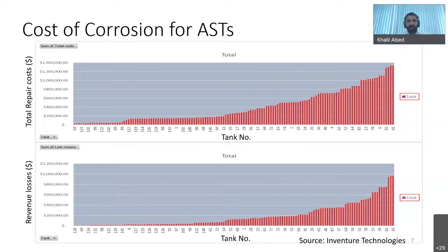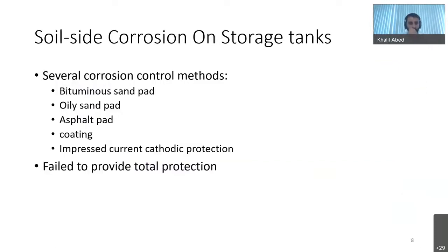And this is where protecting the tank bottom, for example using VpCI technology, can add value to the clients by maximizing the tank performance, minimizing the probability of failure due to soil side corrosion, and rendering the OpEx related to the tank floor inspection, repair, and maintenance as low as possible.